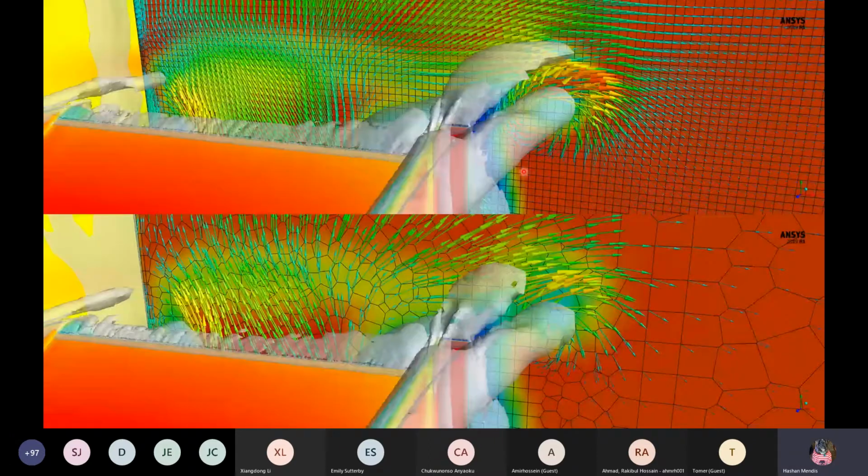You can see here again, taking a slice plane, we've got more elements capturing that vortex structure. I think about mesh elements as information. So we've got a lot more information capturing that structure at the top compared to what's happening at the bottom. Depending on exactly what you're trying to do, you might need to refine these structures. Are you looking at what's happening at the surface, or is something shedding off the surface? It can be a bit different.